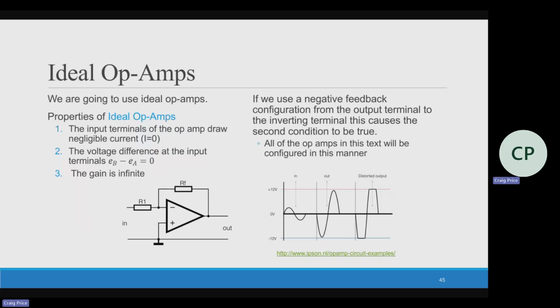Okay, so I know you've got some op-amp experience. It probably hasn't been great in real life. We're just dealing with an ideal op-amp. These are the three laws. Really, we just care about these two: there's no current and there's no voltage difference. From there, we can solve for the output voltage. Like, what's my output voltage as a function of the input voltage? That's typically what we're looking at, input and output.